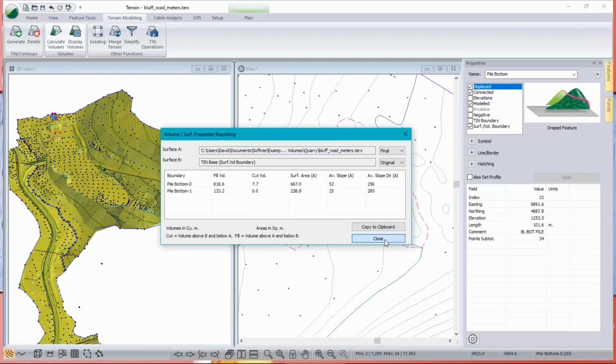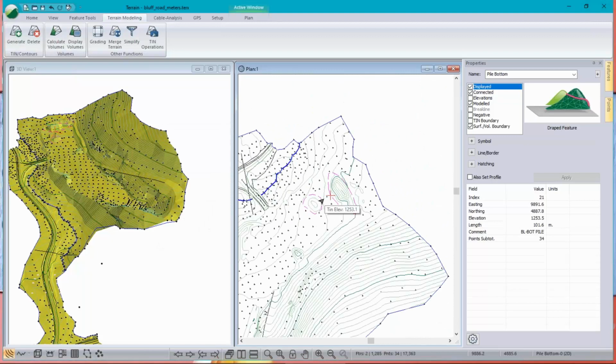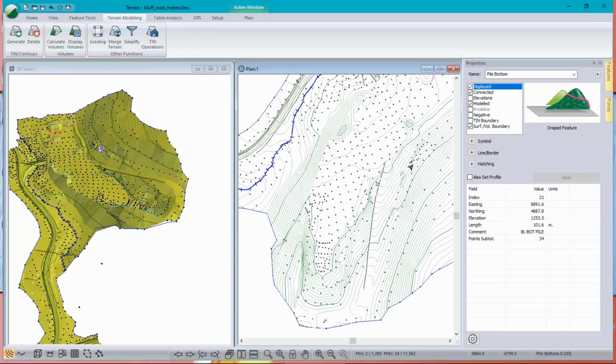Now let's look at another situation. Again, fairly simple. What if I wanted to build a pile and I wanted to know how much material was in that pile and how far it would spread? So let's do that. I'm going to use our grading tool, and I'm going to use that as step 2 in the process of building a site where I'm generating or manufacturing a surface.